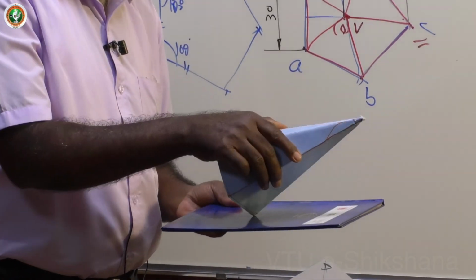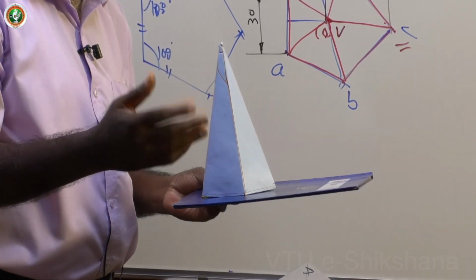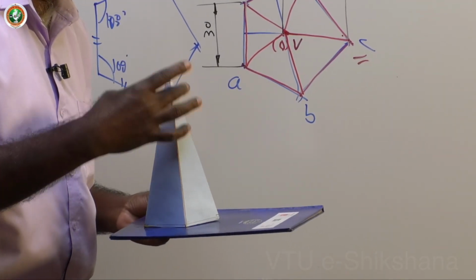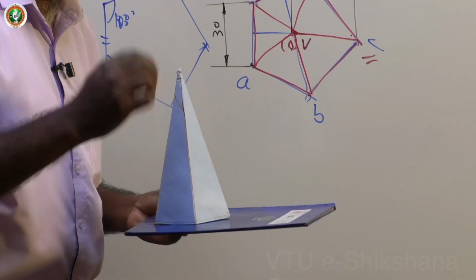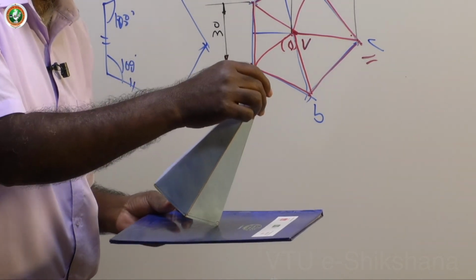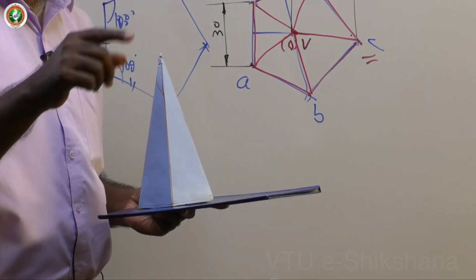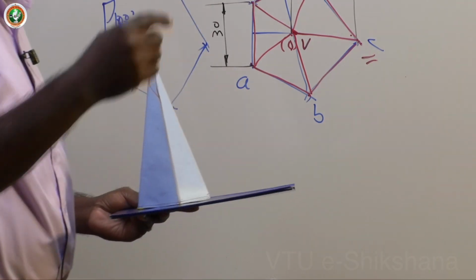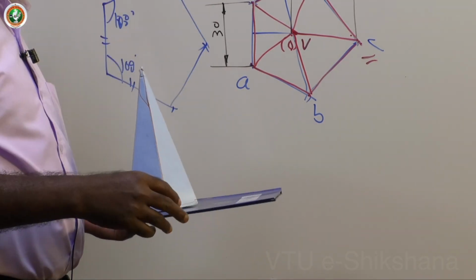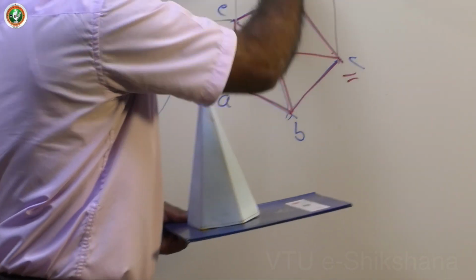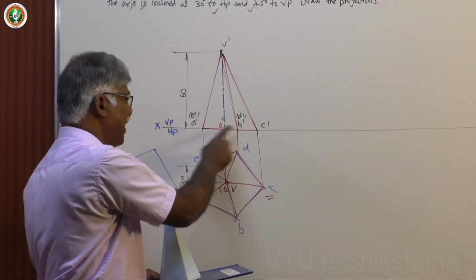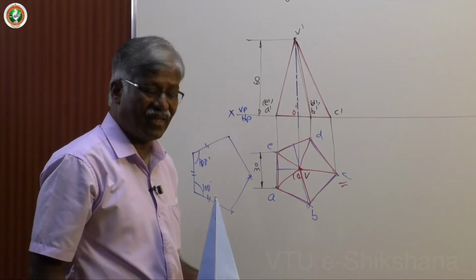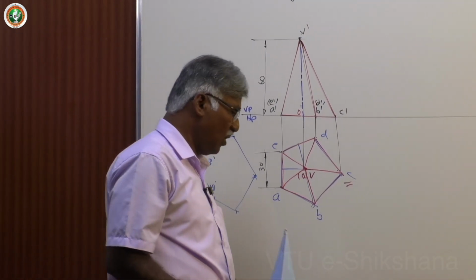First position, second position. Here in case of prisms, already pyramids, I already told you, you cannot take the slant face or slant edge directly for this axis inclination, you take the base inclination. So, axis inclination plus base inclination equal to 90 degree. So, here the axis inclination is 30 degree. So, that actually base inclination will be 60. So, in computer what you do is you move and rotate this figure such that CA as reference you move by 60. So, that you will get axis inclination 30. In this case also manually you have to draw like this.